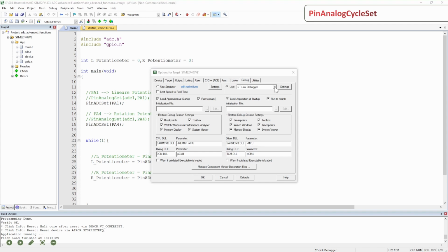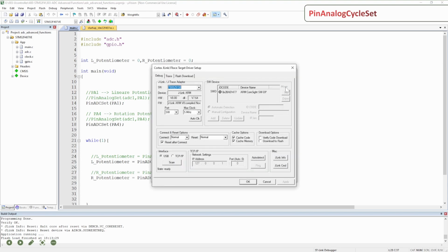So here I'm going to set it up, select my J-Link and go to settings. For the settings, there's sometimes both JTAG or SW. Use the SW connection. You see here that my JTAG is already connected and identified, and that my ARM-based microcontroller has been detected.